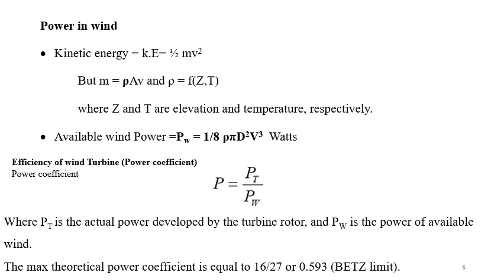Okay, so an ideal rotor, the propeller type blades of proper aerodynamic design, would have a power coefficient approaching 0.59, but such a rotor would not be strong enough to withstand the stress to which it is subjected when rotating at a high rate in a high speed wind stream. Okay, so for the best practical rotors, the power coefficient is about 0.4 to 0.45. Always it should be less than 0.59, so the rotors cannot use more than 40 to 45% of the available power.